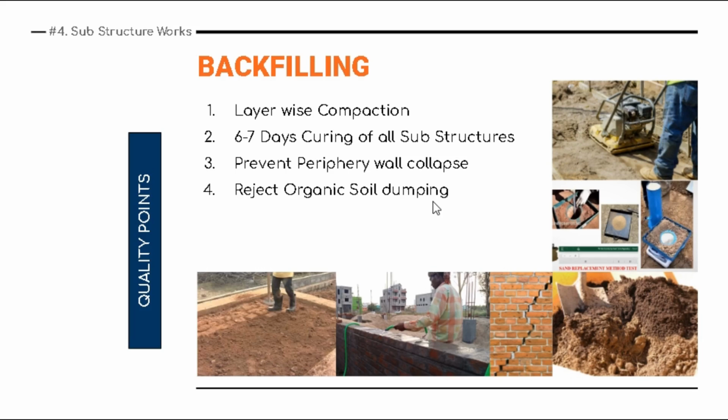Okay, then conduct soil density test. Yes, this is not mandatory in a low risk building, but if you're not using sand, if you're using any other alternatives for backfilling, then go for it, because it's necessary. The basic test that you need to do is the sand replacement test or core cutting test. And the last part is to use a vibratory plate compactor. It is quite important. Otherwise use a small tandem roller, if the area is large.